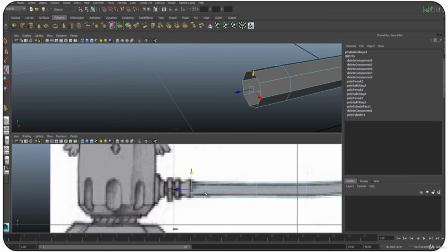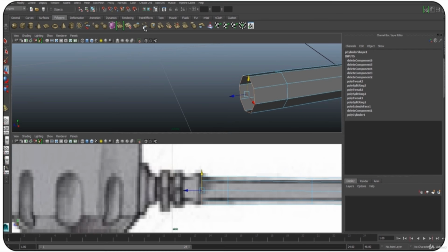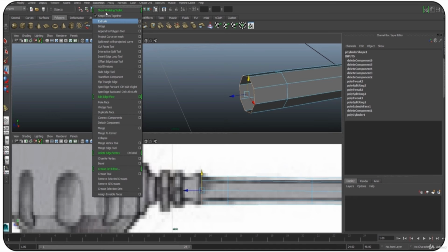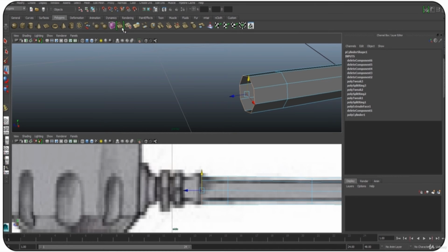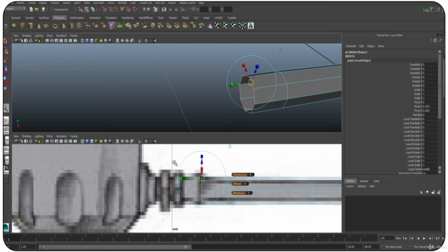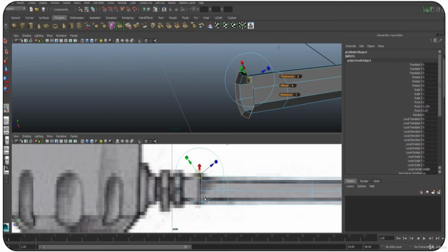So easily you can manipulate your vertices as per requirement. You can use the Edit Mesh and Extrude options from here, and we also have a shortcut. You can use the polygon and hit the extrude shortcut. Now here you can see it's a little outside. Scale up. G for last command repeat and W for move. G for last command repeat and R for scale. G for last command repeat and W for move.